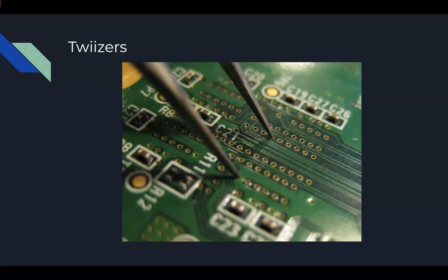But what Nintendo didn't think about is what happens if they glitch out the memory chip lines. Whenever you're getting data from flash or memory, you need to tell it which data you want, and it does that with address lines, which specify which data you want. Everything has a unique address so that you can load it back.